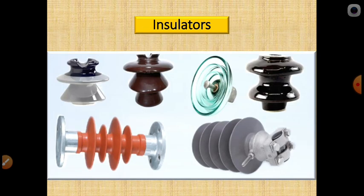Now coming to another important item, insulators. What do we mean by insulators? Insulators are used for supporting the conductors, taking a strain, and suspending the conductors in a required position. In the olden days we used glass insulators. There are mainly three types: porcelain insulators, glass insulators, and the latest, rubber insulators, nothing but PVC insulators. They are further classified as pin type insulators, disc type insulators and strain type insulators.